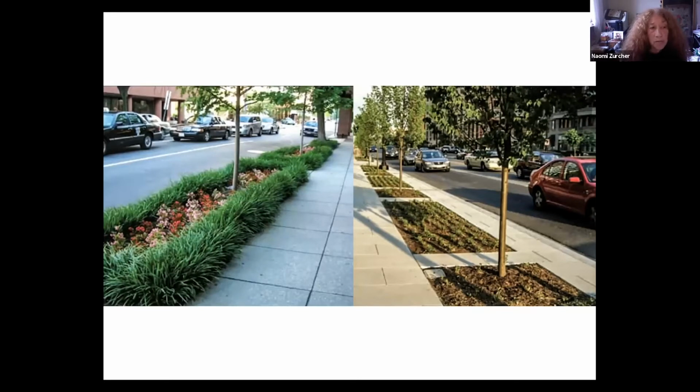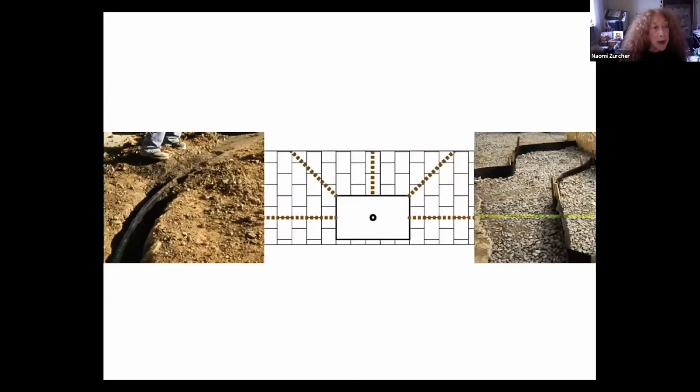Although separated for pedestrian access, that limitation can be addressed through the use of various substrate techniques such as root paths, which allow for continuous rooting. The path should extend at least 30 centimeters into the open tree area, placing the root path opening in immediate proximity to the root ball.